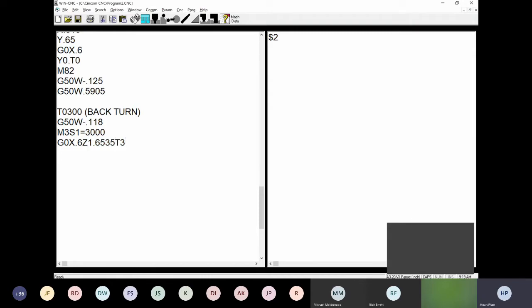And then also tool number 3. Okay, so after that we can plunge down to the diameter that we want, which is right here, the M8, so 8 divided by 25.4 is going to be 0.3149. So the finished diameter for the threading in the back side is going to be 0.31449. That means we need to leave some material for the back side to clean it up.